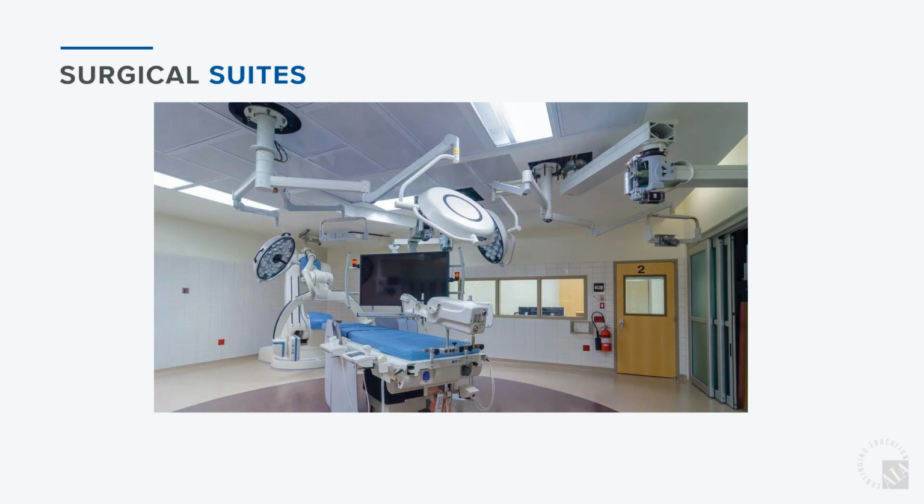So this picture shows you a little bit more of what these types of rooms might look like. And you see all this task equipment just everywhere and anywhere. So the positioning of fixtures eliminates shadows, and it's really going to focus light directly towards the patient. Typical applications are generally a rectangular pattern surrounding the operating table. Surgical fixtures direct light symmetrically or asymmetrically, depending on the type of surgical suite. So again, just trying to get that light at certain angles so we're missing a lot of this task equipment that's in the room. And then green lighting capabilities are offered for many surgical fixtures. So we just talked about the benefits of adding green into your surgical fixtures.